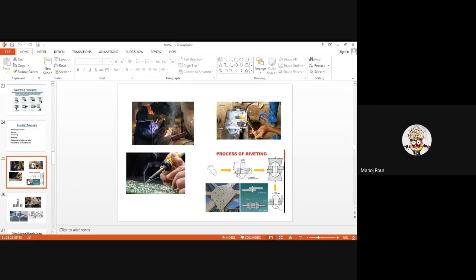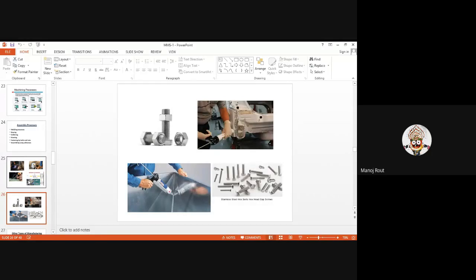That is the concept. The next part is nut and bolt fastening. Basically nuts and bolts are used, but before joining with them, a hole should be made through the drilling operation. After drilling, you put in the nut and bolt and tighten the parent material. With nuts and bolts, you can join similar as well as dissimilar materials. And the last one is fastening, or assembly, using adhesives. Fastening or assembly with adhesive materials is vastly used in automotive companies for large amounts of assembly work.